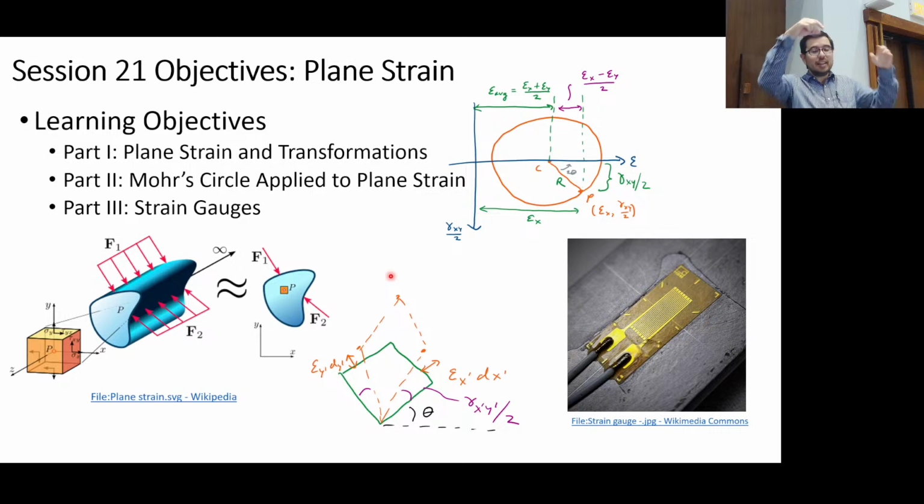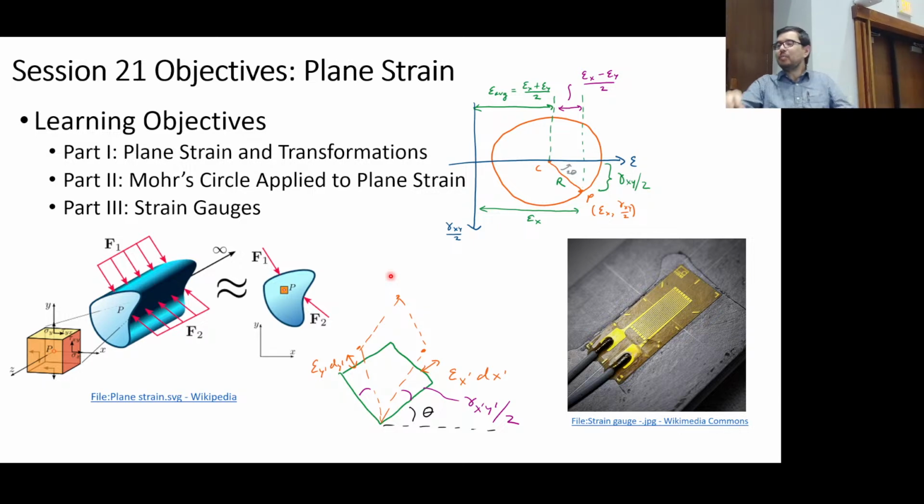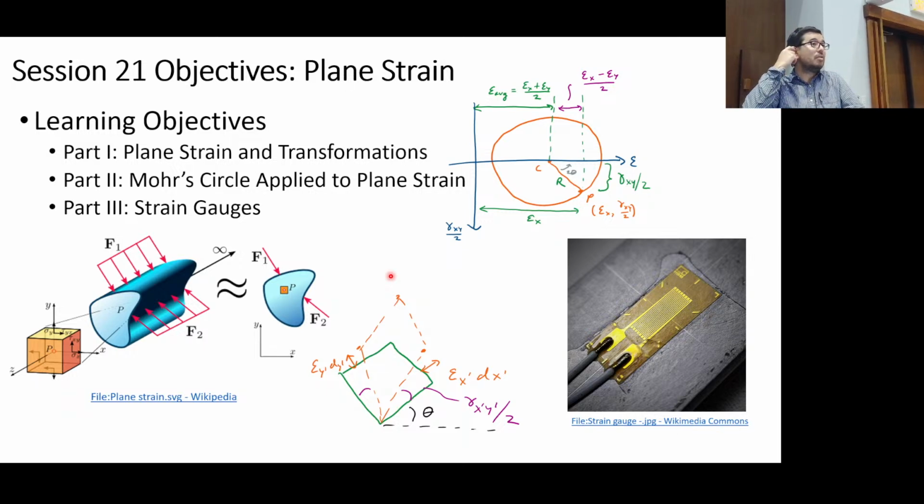And you had a force being applied by the load cell that was telling you how many newtons or how many pounds of force. Then you had the strain gauge on the top and maybe the bottom of the beam, telling you the strain at specific locations. Thank you. Lots of information there. That is a perfect example of how you would use a device for measuring strain. It's very hard to measure stress directly. Why is that very hard?